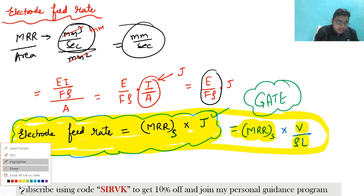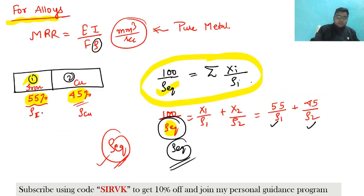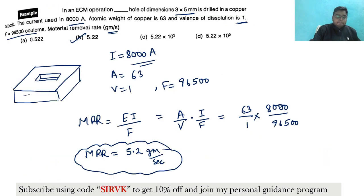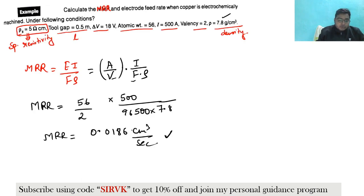Now these things we know. We have seen these things. So the feed rate is specific MRR into V by rho into L. Just remember these things and let's implement them here. What is the specific removal rate you have found out? You know this: MRR by I is actually the specific material removal rate, isn't it? So by doing this you can find it.